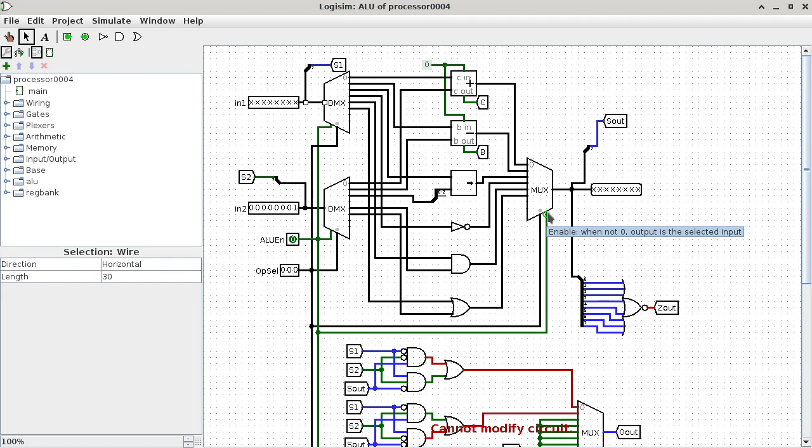If enable is a 0, that means you're telling the output of a multiplexer to what? Which 3 words did we use earlier? Let it be. Let it be. I cannot sing, and you don't want to hear me sing, but it's basically let it be. So when enable is a 0, it is telling the multiplexer to let it be, which means don't try to specify the content at the output. Is that okay? All right.